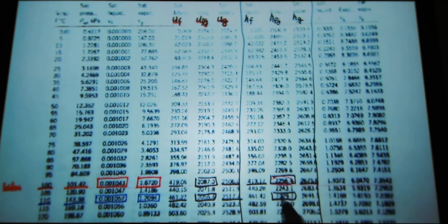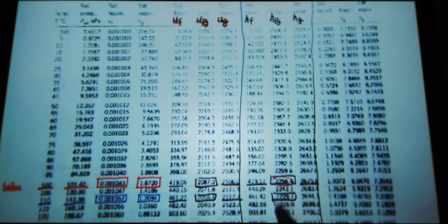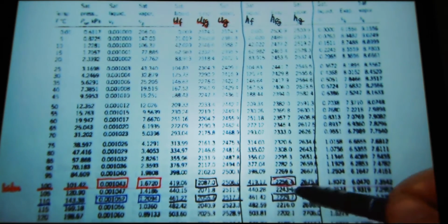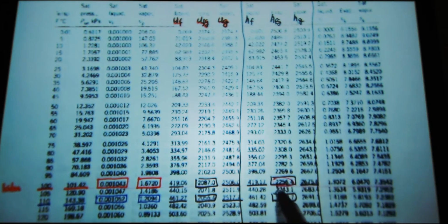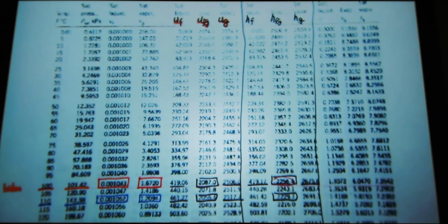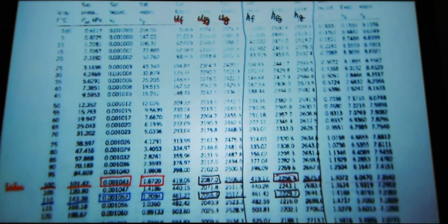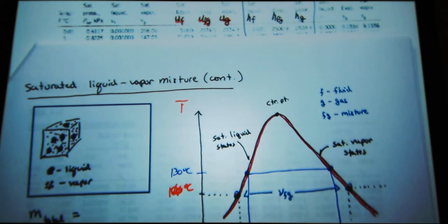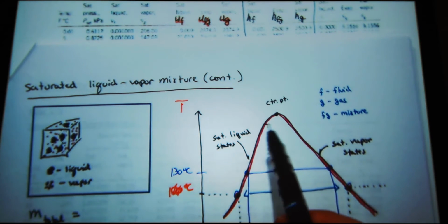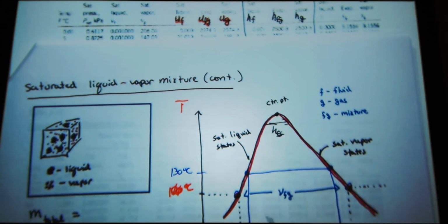Well, no, it's not 2,300. I'm glad I got the number pretty correct. I was just saying it off the top of my head. But it's not just 2,300. It's dependent on the temperature and pressure. Given that in thermodynamics we like to talk more about equations of state, temperature and pressure, they use HFG because really the latent heat of vaporization is a function of temperature and pressure. And this bell curve represents that perfectly. If I plot temperature versus H, my HFG up here is much smaller than it is down there.